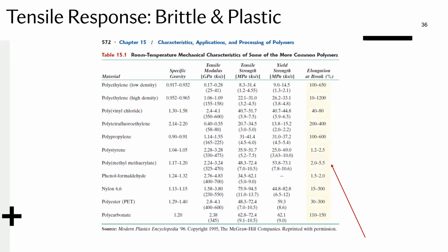So, okay, the next property here is the strength. So we've got the tensile strength and the yield strength. Typically more of a trend in plastics, as you can imagine, because those actually yield. The brittle polymers don't, so they only have an ultimate strength. So again, if you look at these, you can kind of see that, right? So you can see that here, for instance,